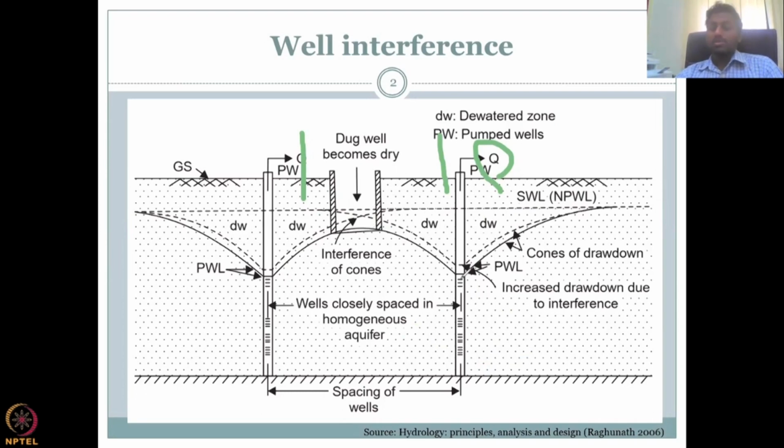but because this pump has been pulling water, and same as the other pump, in the borewell, from a very deep aquifer. While it is in the deep aquifer, and the connection is there with the shallow aquifer, water will still be pulled. Remember, I said most of these bore wells do not have a casing. It's too expensive to have casing, which means all this area is available for water to push into the well and then get sucked out due to pumping.